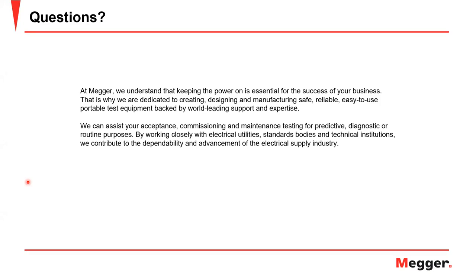On the other hand, if the load of that system is mainly made of three-phase loads, like induction motors and things like that, you do not want by any means to have single-phase reclosing. However, single-phase reclosing is attractive when you have, for example, residential loads and places where you have a lot of customers that do not use three-phase power.